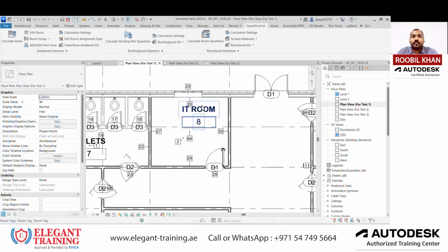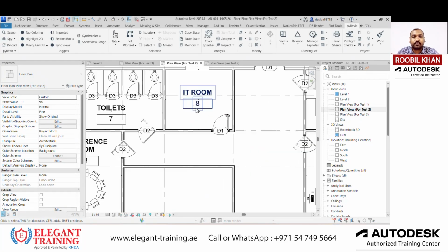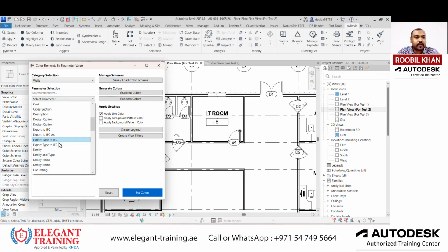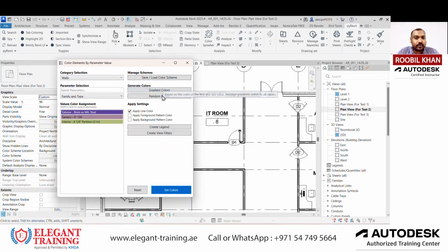And the next plugin, we will be going to Revit. Here you can see Revit is already installed on my laptop. If I want to categorize these walls by family, I go to Color Splasher, and from here you can select the category. I choose the walls here and I can select the parameter. In this case I choose family and types. As you can see, Revit automatically gets the information on the type of the walls. If I want to change the color scheme, I can also do that. If you need gradient colors, you can also choose gradient colors here. Once the colors get generated, I can set the colors here.